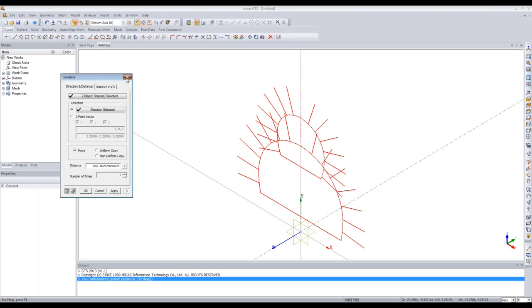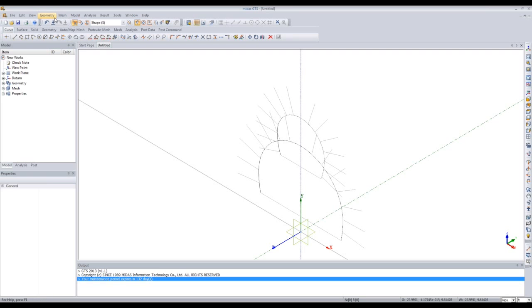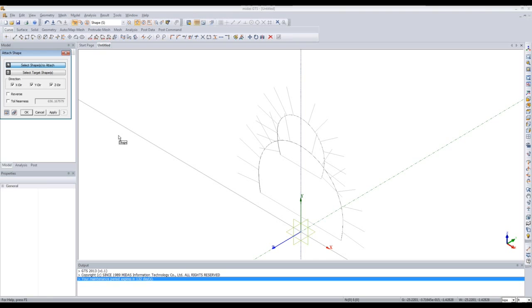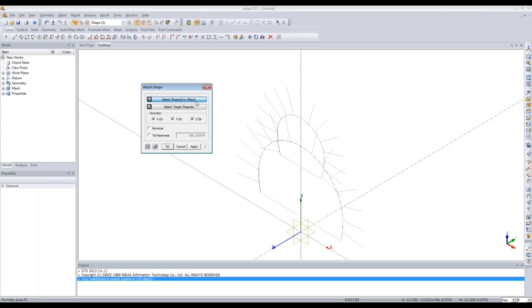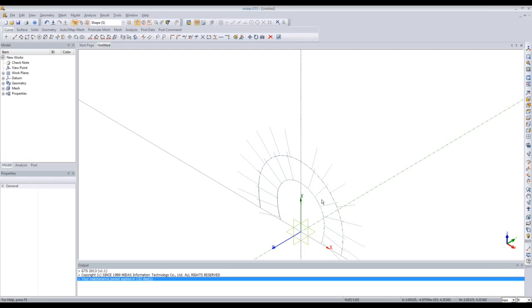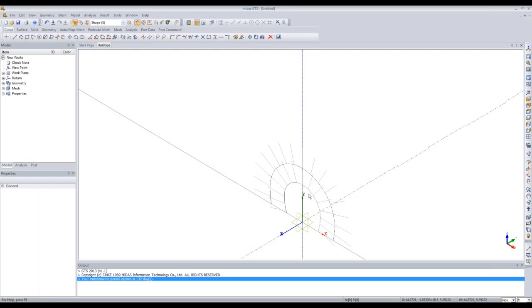What you could do actually, in order to do it faster, is go to Geometry, Transform, and then Attach, and then simply select the shapes that you'd like to attach. So we'll select both. And then select our target shape. So instead of a solid, let's choose a point, V, and we'll choose the origin. This is a preview of what it'll look like. Both shapes will be translated to the point of the origin. So click OK. And as you can see, the translation was successful.